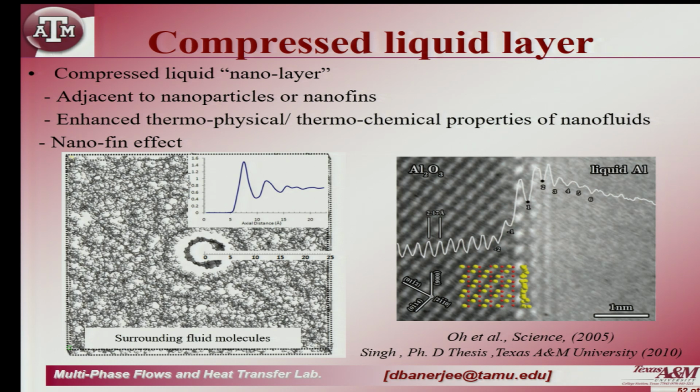What is the property of FCC solid aluminum? I do not know. So, in other words, this semi solid layer that I have formed here has properties on the nanoscale that are vastly different than you would get in the bulk phase. Same thing about the surface tension. The surface tension that you get in the bulk phase might have a different structure than the surface tension that you get on the nanoscale, exactly on those same lines, okay, because the container now has started affecting the property of this layer.